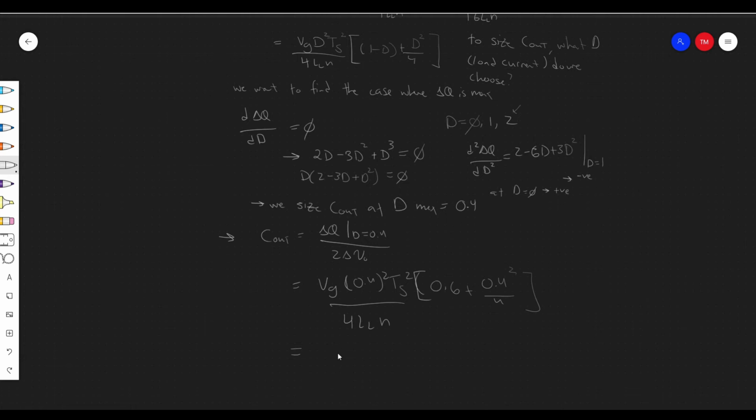And solving this, it gives you an answer of 109.2 microfarad. So obviously you can't find an actual cap with this value, but this is telling you the minimum it needs to be to constrain your output voltage to this value. And to be clear, there's actually 2 times 50 millivolts in here from the specification. So this is the C you need.